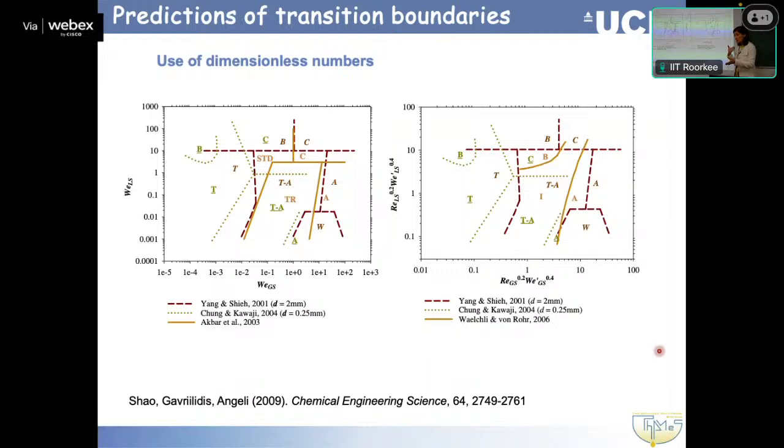In small scale systems, the inlet conditions, the effect of inlet conditions, are even more important. So all of these studies here, they don't use identical inlet conditions, and the inlet might play a role. So when you change orientation, apart from gravity coming in and certain symmetry in the flow, it could also be the way your inlet conditions are changing. So I would say you can assume that if the gravity Bond number is low, it should not play a role. It should be the same. So if you have Taylor flow in horizontal, it should be Taylor in vertical. But if you're very skeptical, you need to check that.